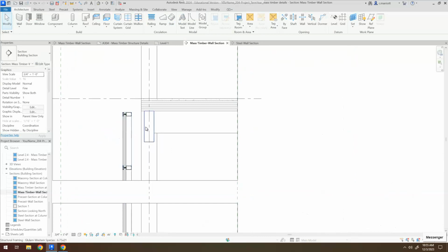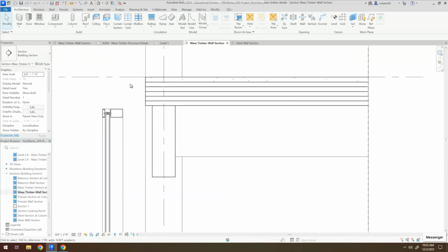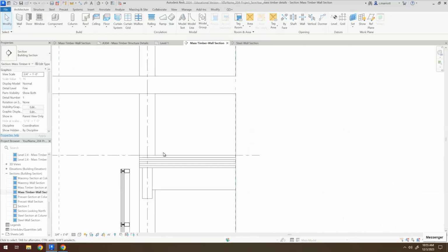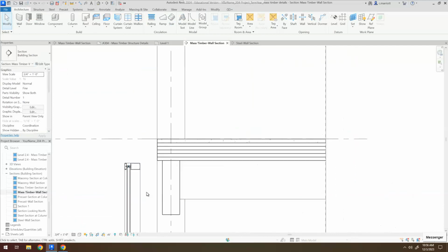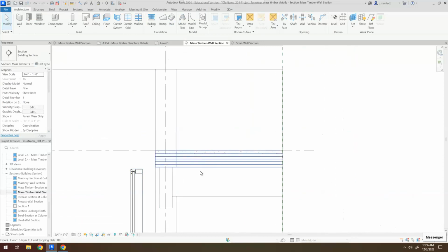Okay, now we can begin working on the wall assembly that will be from level 2 to level 3. And just to give you some overview of what this detail is going to look like. We terminated the CLT floor system aligning with the column beyond. But what I'm going to do is extend it out a little further, and we will have the CLT wall assembly that's sitting above. It'll be directly above the storefront.